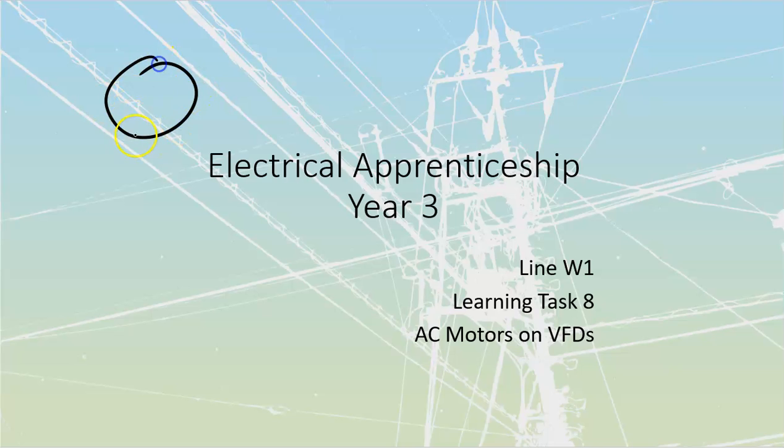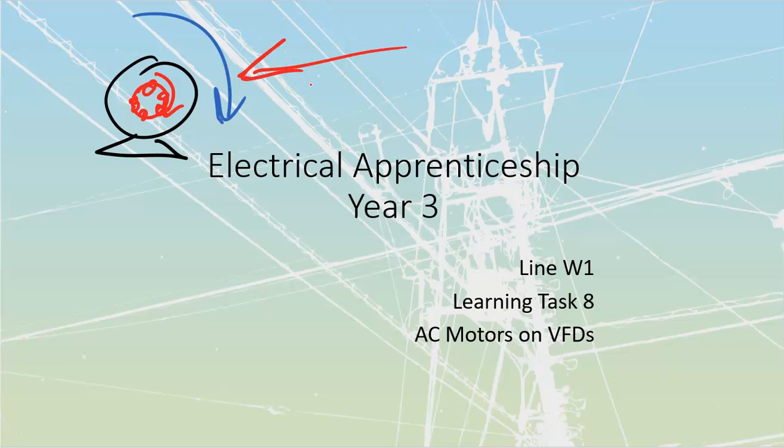That rotating magnetic field going around the stator then cuts across the rotor, where it magnetizes and creates current flow inside the rotor bars, which then causes the rotor to catch up and follow. We know that ultimately the speed of our synchronous field is related directly to the frequency that we operate at.